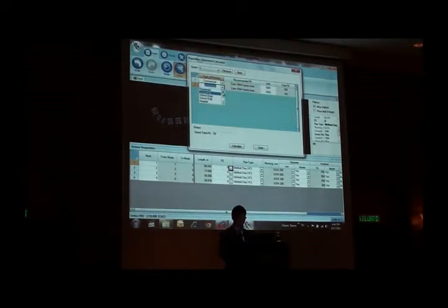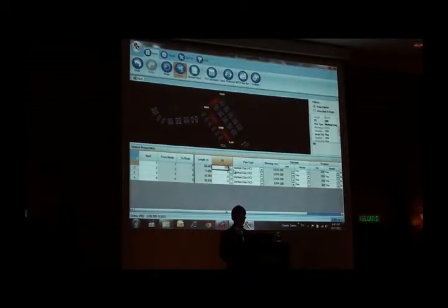Let's say this manhole also covers residential. Residential is 5 PE per house. Let's say you have 10 units. So we get 50. Calculate. So we get grand total PE is 200. When we close it, so we can see automatic update here, 200. Okay. So I just apply all. You can right click and apply all. That means copy down. Okay.